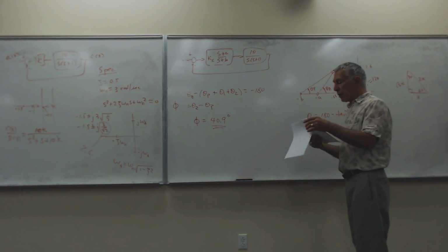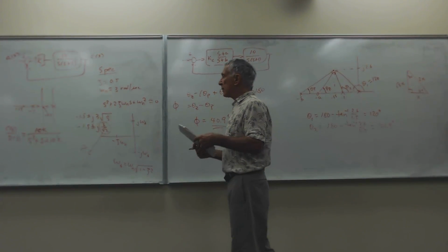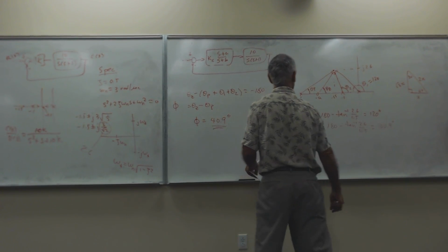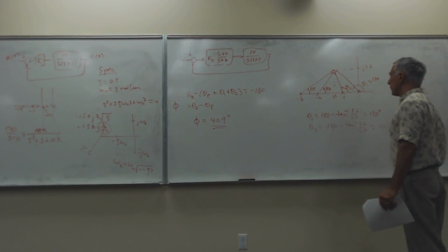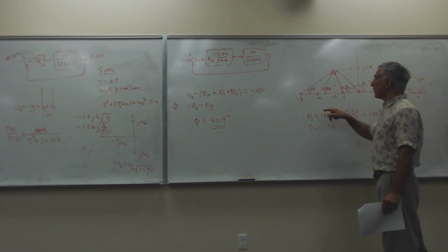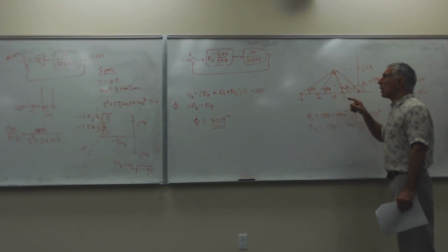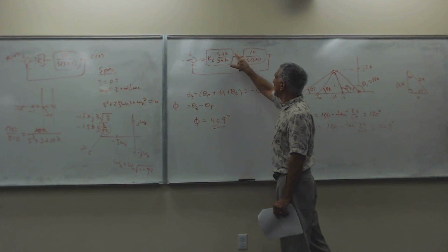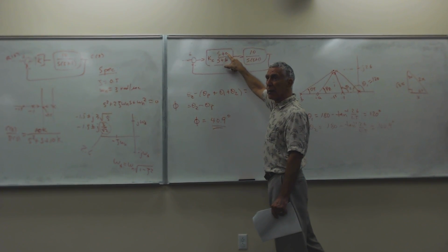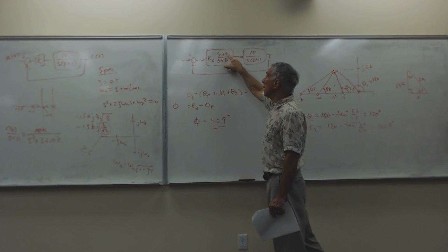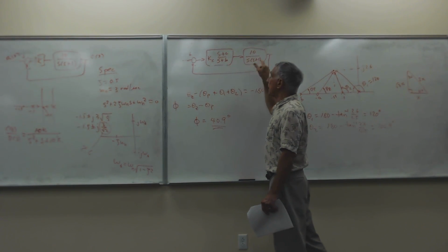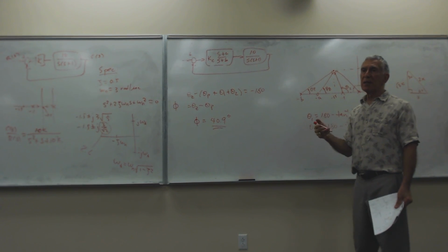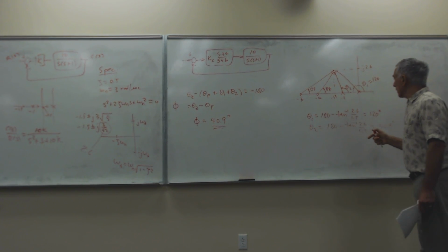So the book goes through 2 methods. The second method is what's called pole zero cancellation. So actually, with pole zero cancellation, the pole of the plant is canceled out by the zero of the compensator, right? So in other words, we're going to set A equal to 1, and that's half the problem, right?